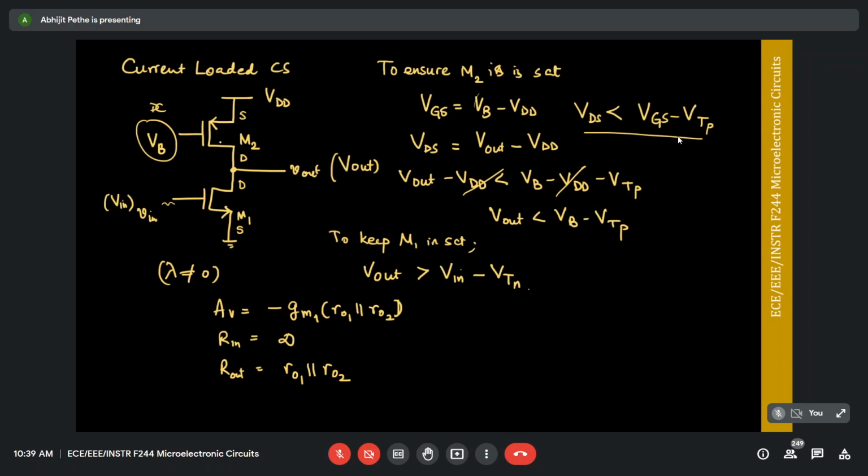So what does the current source mean? Current source means that it supplies a constant current no matter what the voltage across it is. And so therefore what's happening with this PMOS is, as this voltage fluctuates, the PMOS is essentially being replaced by a small signal resistor. So this PMOS is just working like a current source. If I had a very long channel PMOS whose R0 was very, very high, then this would have looked like a perfect current source.